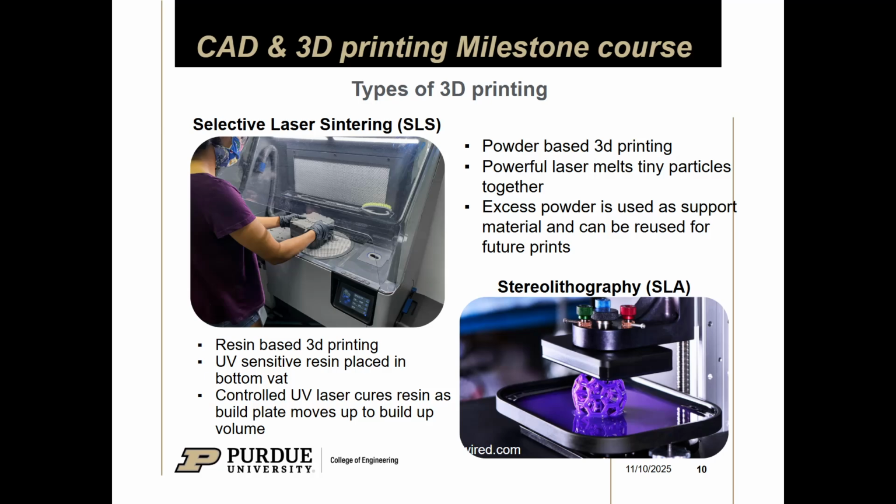In terms of types of 3D printing, there's a bunch of them out there. I'm just going to list 3 today, but there's something called SLS, which is more on the industrial scale. It stands for selective laser sintering. Basically, they take the raw material in the form of a powder, and then they use a laser to precisely melt a really small area of the part. And then they'll cover that solidified layer with more powder. They'll shoot a laser at it again, and they'll do it hundreds or thousands of times until you have your part, right? So it's pretty awesome.